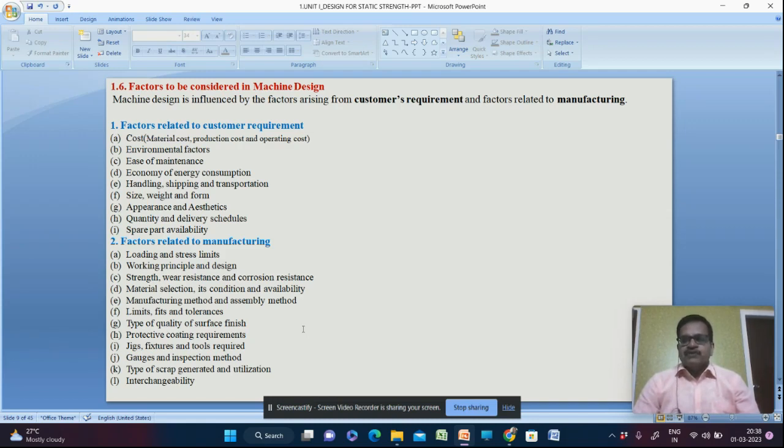When you have machined that, you will have definitely a better surface finish. When you are going for grinding, you will have much better surface finish. When you are going to have some operations like lapping or honing or reaming, depending upon the outer surface or the interior surface, the surface will become much smoother, and it is known as mirror finish.